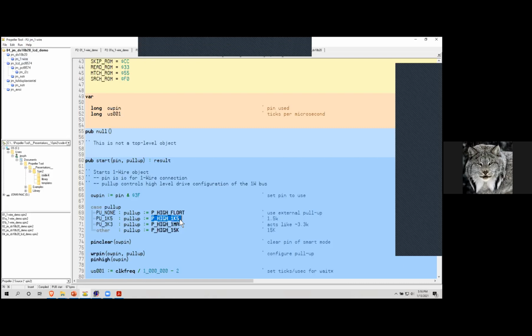You're just adding more keys. Right. Yeah, it's write once, I guess. And then the EEPROM and NVRAM ones have up to like 64K bit. So 8K bytes of data could be stored in this tiny little button. Read and write is probably pretty slow, but it's still a lot of data that could be stored in there.